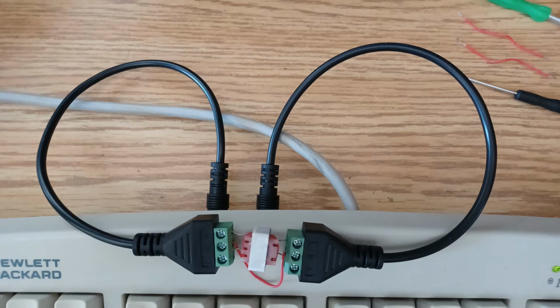So in this example, the device under test is this simple isolation transformer that I use a lot in all my projects. This is a 600 ohm to 600 ohm one-to-one isolation transformer, and in this case it is the device under test. We use one channel to test the transformer, and the other channel is connected straight from the output into the input for the reference in the software.